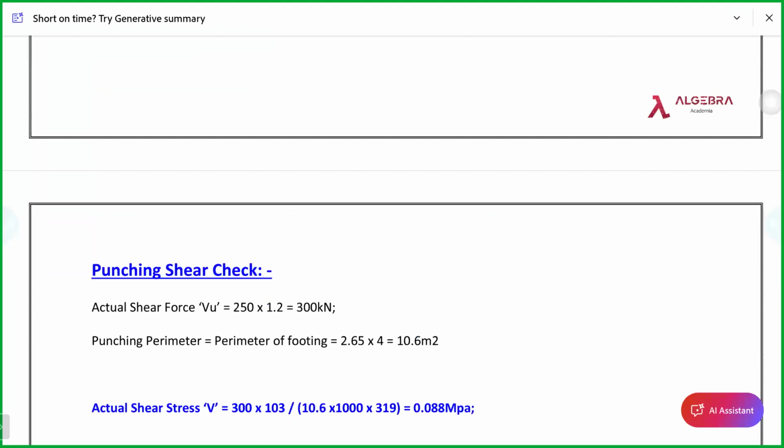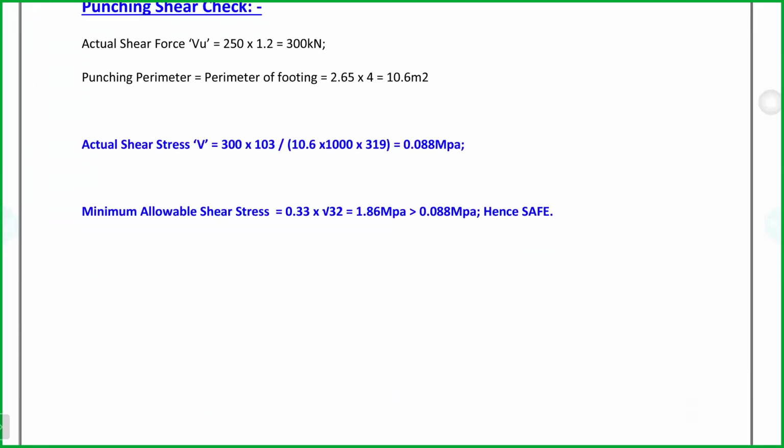One more thing in concrete structures: how to determine whether it's a fixed end or a simple support? In general, concrete to concrete connections are all fixed, by default. Simple supports only happen in steel, because in steel you can design the bolt and plate either to provide moment or not to take moment.